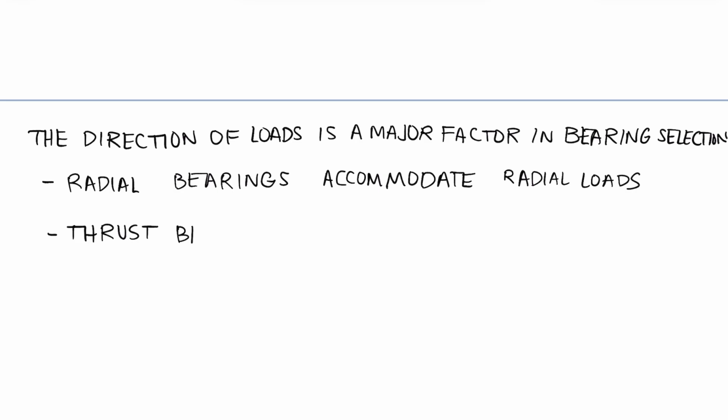And thrust bearings accommodate thrust loads, or we might call them axial loads. And the contact angle is what determines whether a bearing is a radial bearing or a thrust bearing.